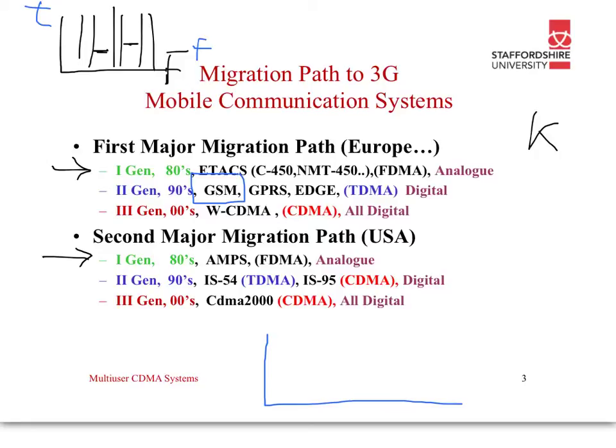If we had pure TDMA, then every user could access the entire channel for specific periods of time. Then the number of users was limited by the number of slots that we could have, because obviously if we waited too long, then we would experience delays, because we would have to wait too long for our next slot to occur.